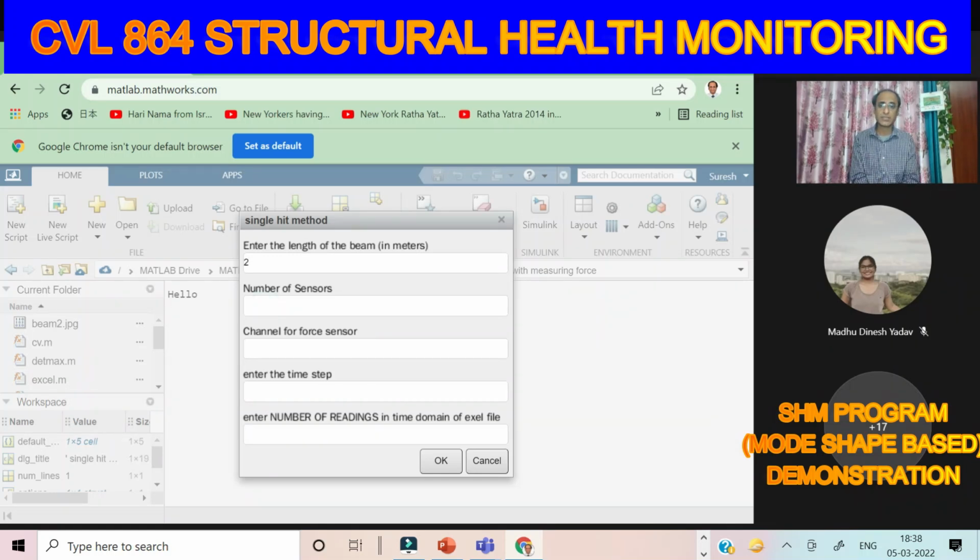Then it asks for the number of sensors. We have 7 sensors. Then it asks for the channel in which the force measurement is recorded. We have to specify that. Then it asks for the time interval, that is 1 millisecond. And then it asks for the total number of readings, which is 2500. All the input files are in the folder which I'll be sharing, and it may happen that some of the files are in an earlier version of Excel. In case you get a runtime error, all you have to do is open those files in Excel and save them with another name. Some of you might get a runtime error; that is the way to fix it, because the files are earlier versions.